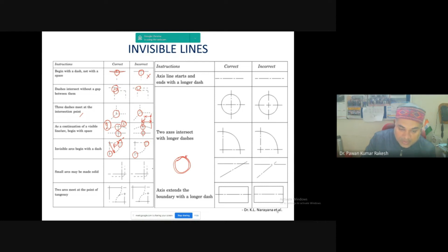So in that case, if you want to do the chamfering, then we have to follow the complete line without the dash line. We need not draw the dash line, but we have a complete solid line showing the radius, or you can note down the radius is 3 mm. If you have this, you will be able to use it on the machine drawing part.